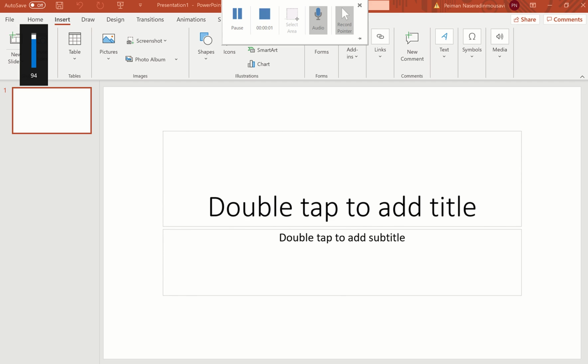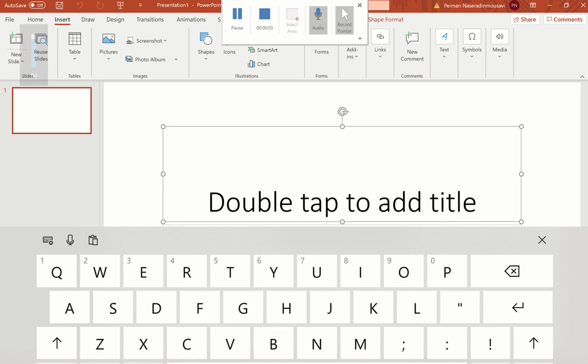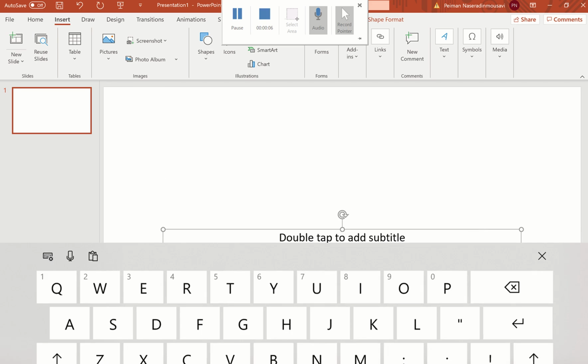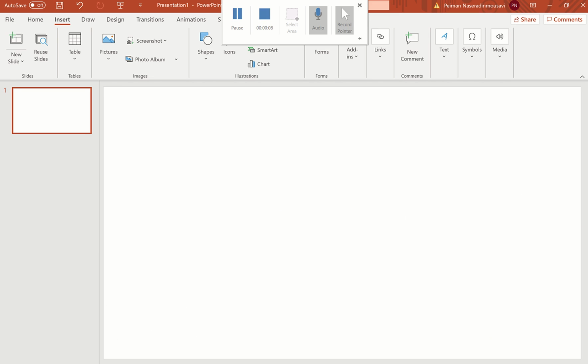Okay guys, in the previous class I did the example of the inverted pendulum, but that has no integrator in the open loop transfer function, and we added zeta as a virtual state variable, so it increased the order of the system to n+1, or 2+1 was 3, and we designed the controller.